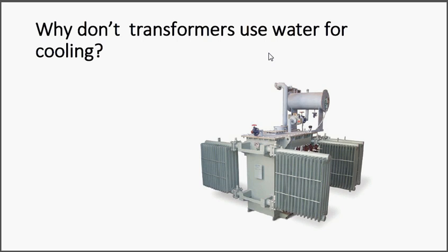But one thing you can see, and this is sort of the downside, is that oil, once mixed with other stuff, can burn. So when transformers go, because something has gone dramatically wrong, they actually burn up, and they go up in a big flash with the oil around, and it looks quite scary. Obviously, with water you wouldn't have the problem, but they would go a lot earlier. So anyway, that's the reason. Electrics and water generally don't mix.